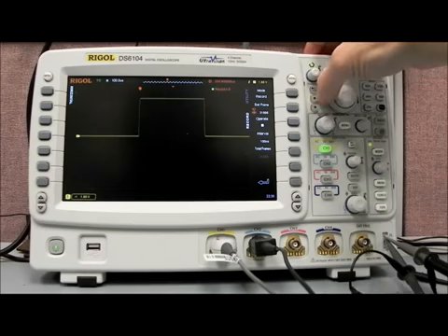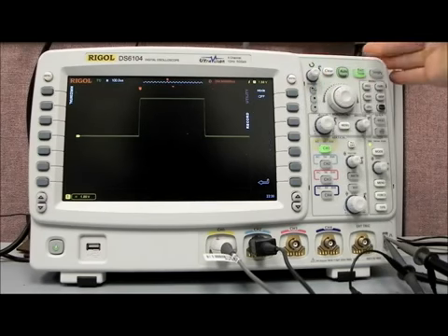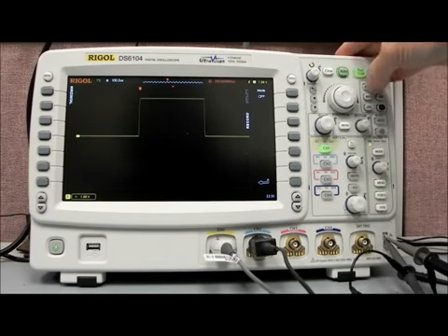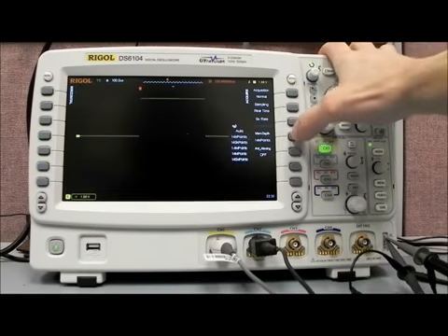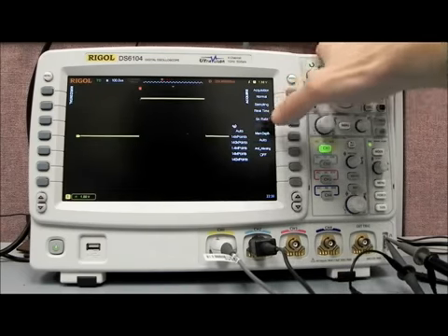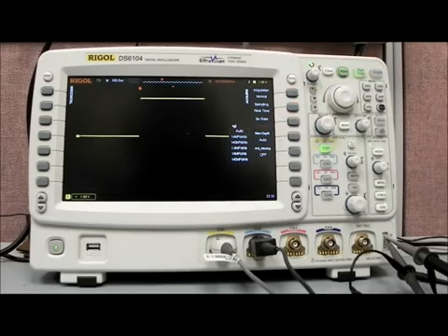In order to access the data collection, most of the time the scope is going to be running in auto mode, but if you press the acquire key, you can go to the memory depth. Again, most of the time the scope is set in auto, and in auto it's going to automatically decide the best sample rate as well as the best number of data points to take for that particular horizontal time frame.